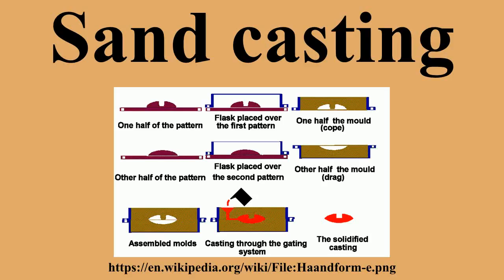Olivine, chromite, etc. are used because they do not have a phase conversion that causes rapid expansion of the grains, as well as offering greater density, which cools the metal faster and produces finer grain structures in the metal. Since they are not metamorphic minerals, they do not have the polycrystals found in silica, and subsequently do not form hazardous submicron-sized particles.